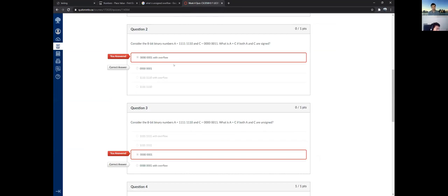Yeah, that makes sense. So the thing is, you actually got the process correct. You just didn't understand when the overflow happens or not. You did the right process. It's just that in one case the overflow happens, because the addition of these two numbers shouldn't lead to 0, 0, 1. It leads to overflow. But when you treat them as unsigned, then one of them is negative, and that's actually a correct answer. There's no overflow there.